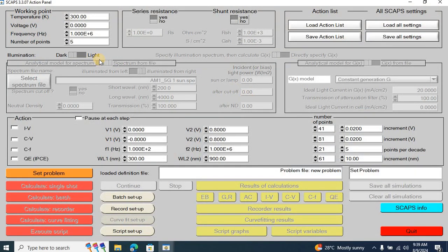First of all, in SCAPS 1D, we set up the simulation environment for the simulation of the solar cell. Initially, we set the temperature to 300 Kelvin, but later we are going to vary it in the range of 300 to 350 Kelvin. I'm not simulating the effect of series resistance and shunt resistance at this point. We are going to do that at some point later.